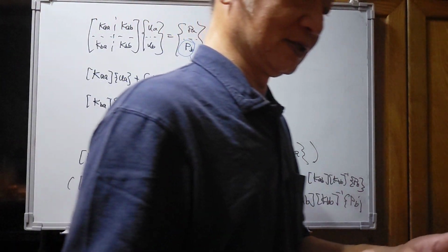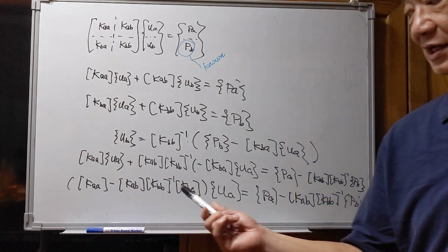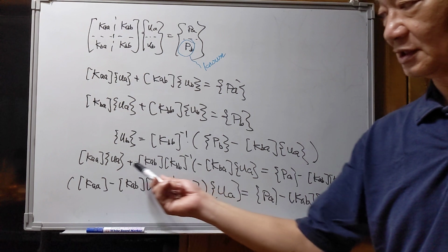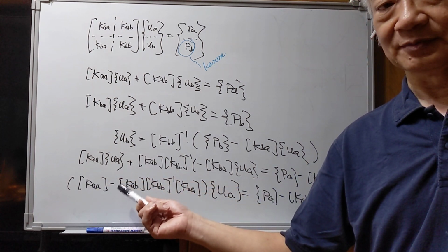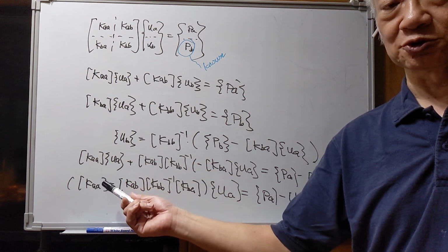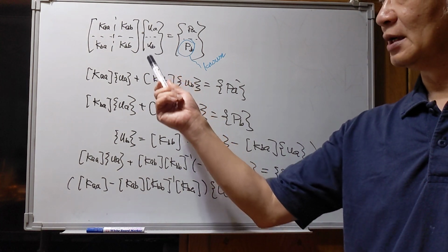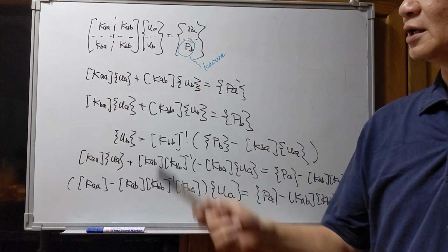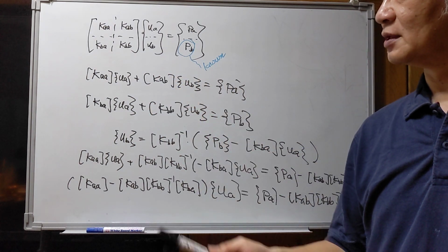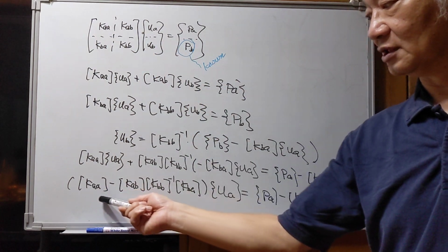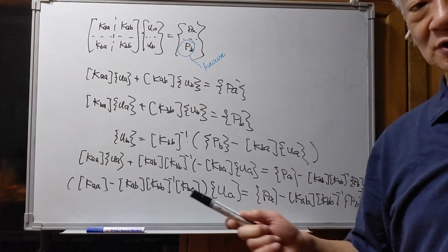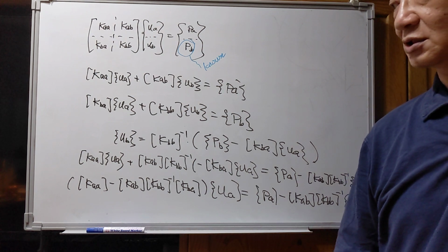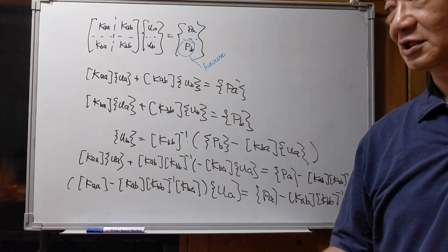You should pay attention to the last equation. Usually we say that's the result for the condensed matrix. After you calculate all the matrix in the parentheses, you will see this matrix has smaller dimensions. For example, for the plane frame problem, the original matrix is a 6x6 matrix. If UB contains 2 elements and UA contains 4 elements, then the matrix in the parentheses will be a 4x4 matrix, which is smaller than the original 6x6 matrix, and usually we say it is a condensed matrix.